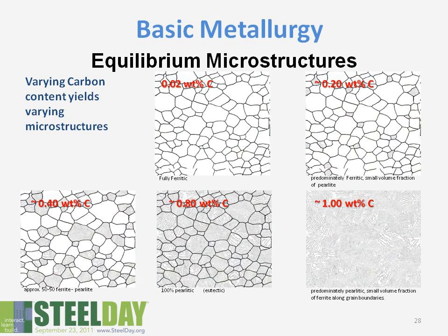If we were to look at different steels with different carbon contents under the microscope, we're going to see different amounts of ferrite and pearlite occurring. So if we go below 0.02% carbon, we're going to have a fully ferritic structure. As we increase the carbon, you're going to start to see some random colonies of pearlite.